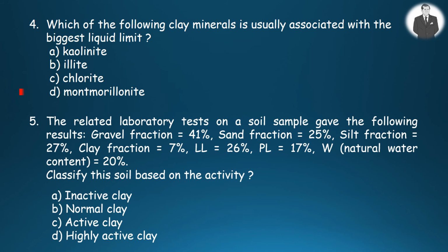Remember the activity equation, which is very simple, a ratio between plasticity index and the clay fraction. Figure it out, compare your result with those listed in the related table and classify the soil. Yes, the answer is C, active clay. Good for you.